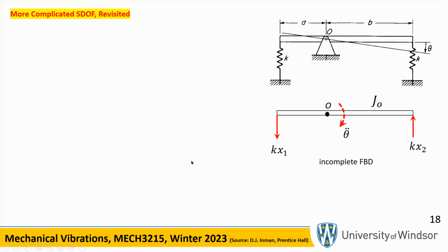Now I'm going to go and do this problem, which was done in lecture 4 also, except that we're going to use the energy method. So we will be using this angle theta as the degree of freedom. It's a single degree of freedom. Once you give me this theta, I know everything about the assembly. You could have used the vertical displacement of this right point, but that would have been another alternative way of doing the problem. But the natural one is using this theta.